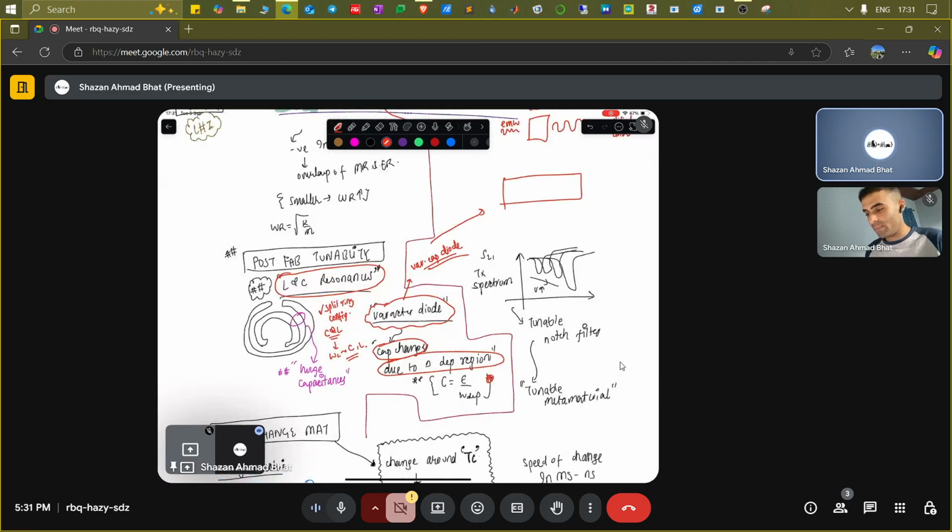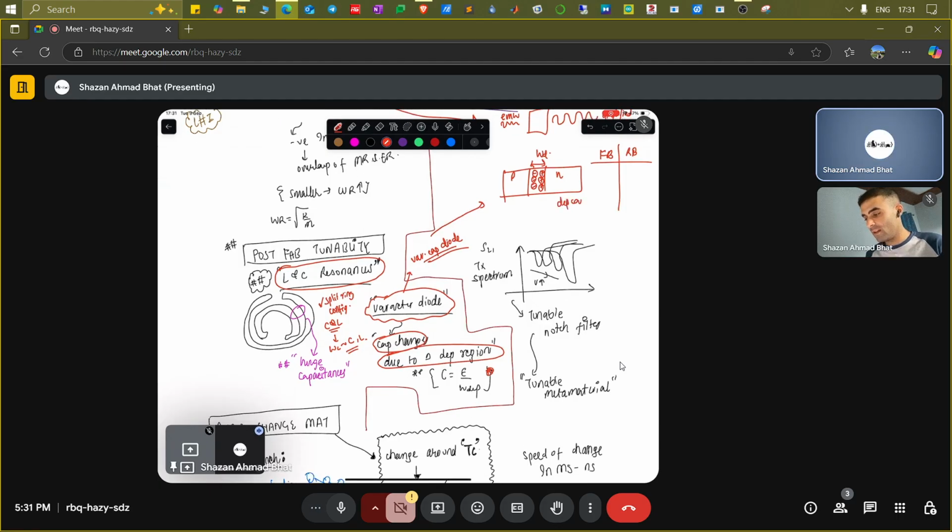So if you talk about a PN diode, let's say this is P, this is N, you have positive immobile ions in the depletion region. So this is the width of the depletion region. You know what happens in the forward bias, what happens in the reverse bias. This is just basic device physics. You talk about depletion capacitance, and you talk about junction capacitance. They occur in forward bias and reverse bias regimes, and that means you have charges present here, and this immobile region acts like a dielectric, and you have the capacitance associated with it even in reverse bias and also in forward bias.